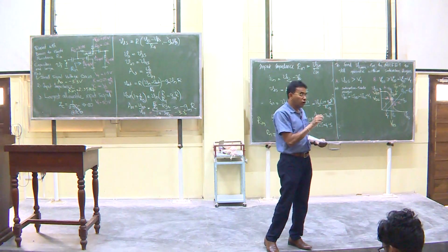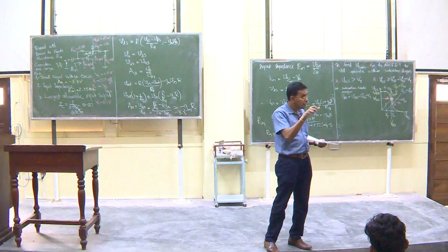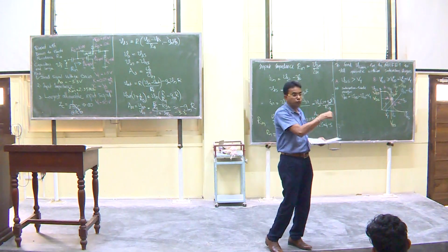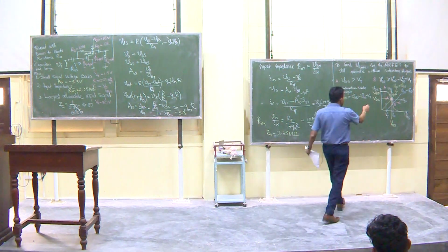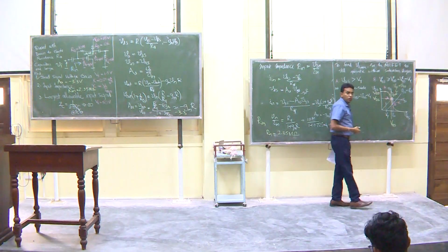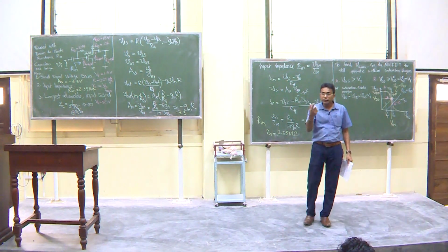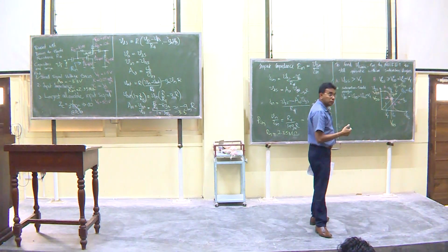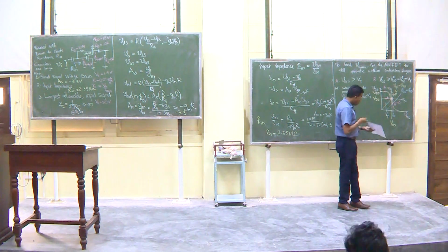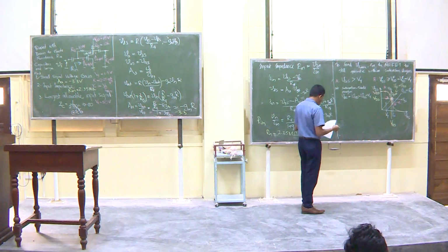If Z is smaller than X, then I have to go with that Z, because it will go into cutoff before it goes into triode. So, for example, if it operates right here, then with a small input it will go into cutoff rather than triode. So we need to find this and that. That is basically what we are trying to do now.